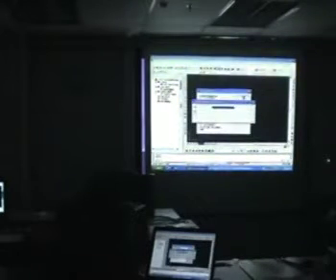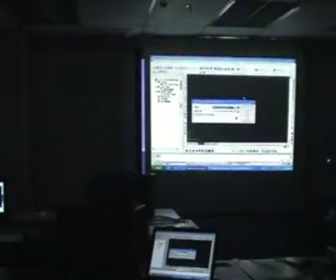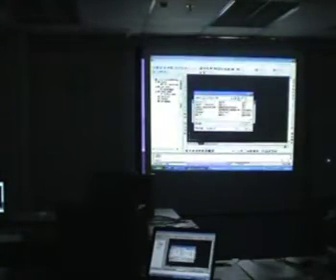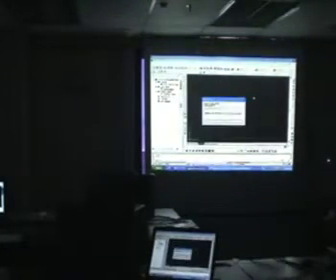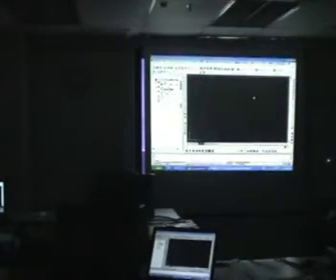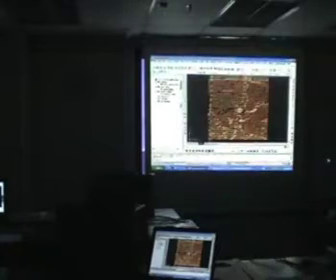But for this particular case, it's really easy. So we're just going to use ENZ comma delimited. I'm going to browse to that file. I'm going to add this to a point group called OGL, original ground level. I'm just going to click OK. And what it's doing now is converting that text file into Autodesk Civil 3D points. I'm just going to zoom in to show you the points.